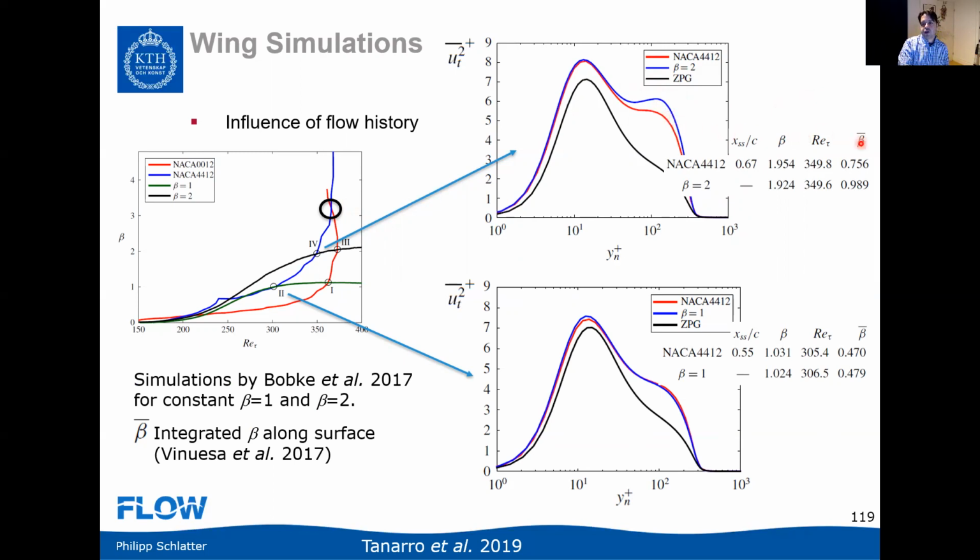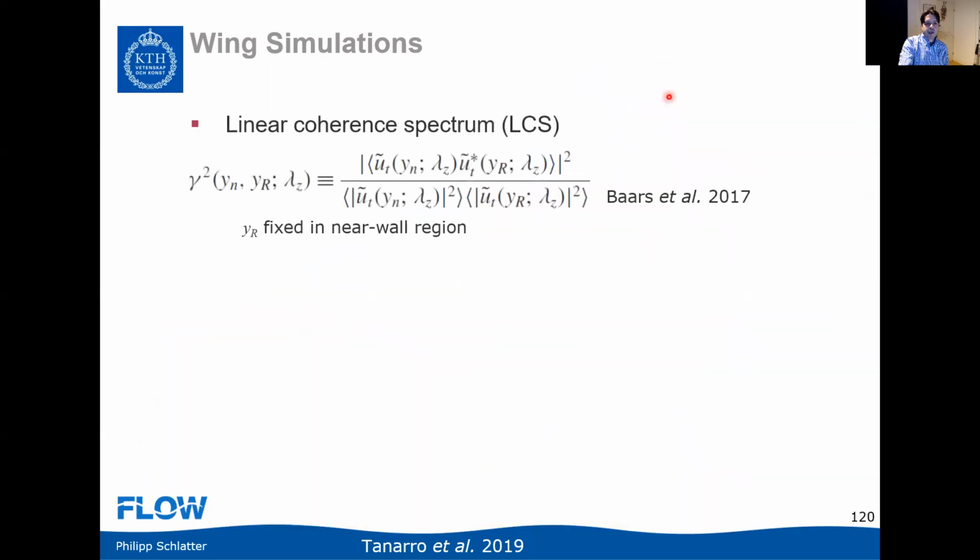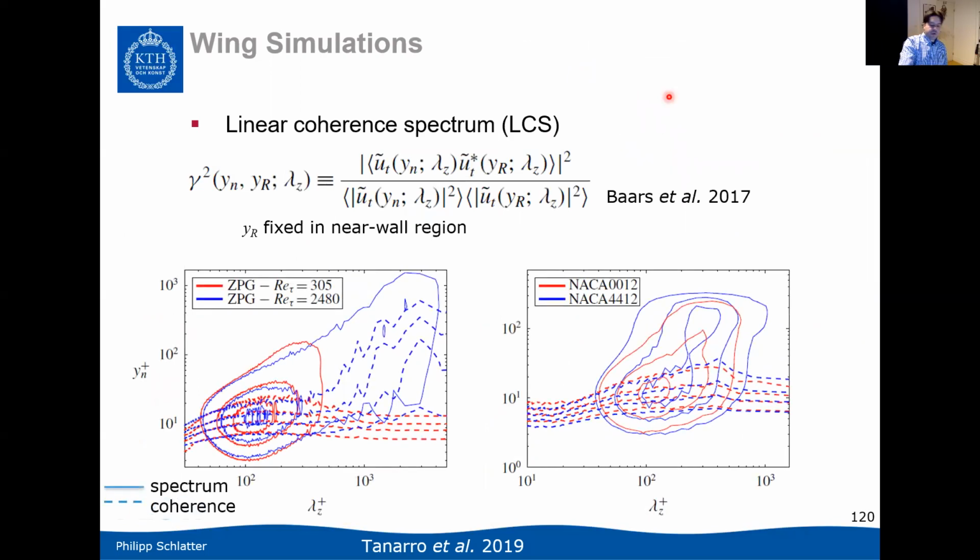We tried then to quantify this with an integrated pressure gradient coefficient, beta over bar, where we can essentially see that if those parameters are similar, then the outer region would be very similar too. If those are not similar, you would progressively see a larger influence if you had a higher pressure gradient. So this is one way of analyzing what happens in pressure gradient turbulent boundary layers.